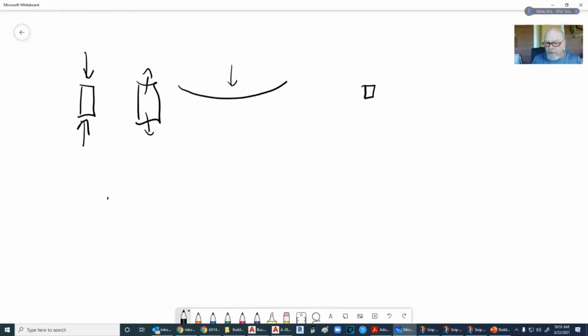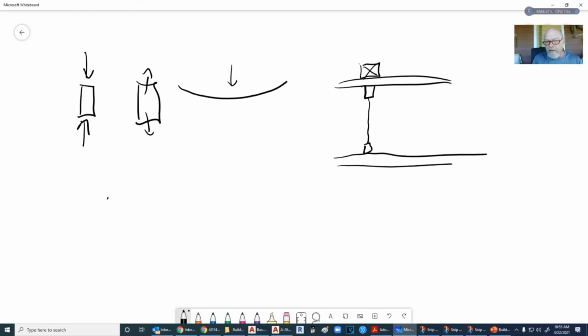So we have our I-joist, and let's say that we have a wall that's going to run underneath it, and then maybe we have a wall that's running perpendicular on top of it. The weight from this wall pushing down can buckle this piece of OSB in here. So what we have to do is take 2x4 pieces and place them right up beside it. And what happens is we're transferring that weight. That weight is coming down. Instead of going across here, it's going to transfer over and then on down, and this is called a squash block.